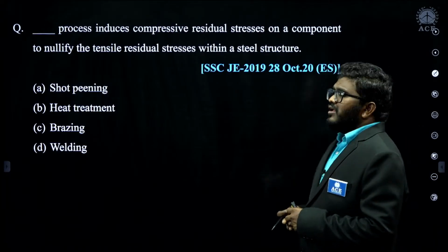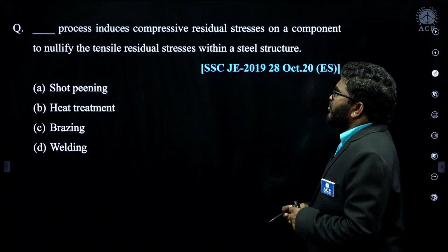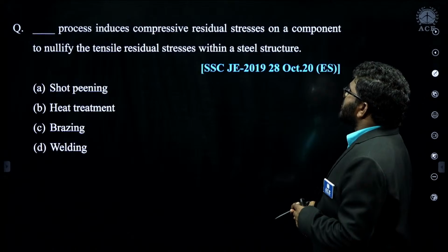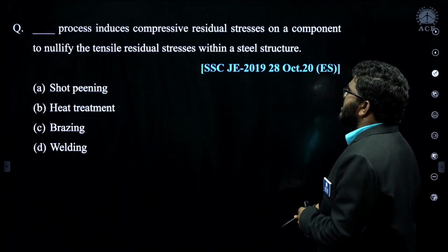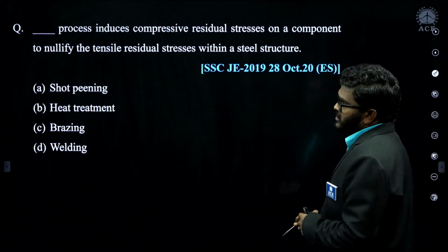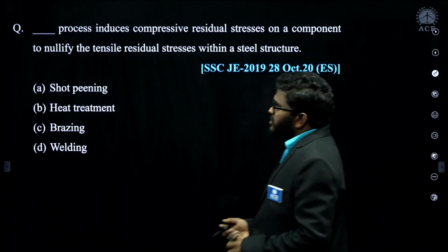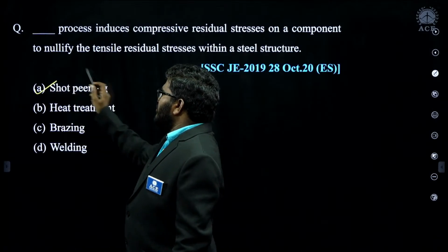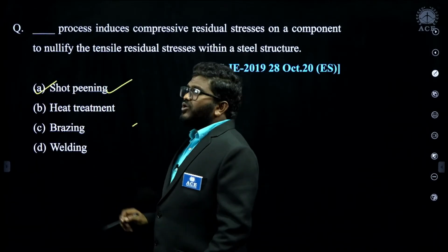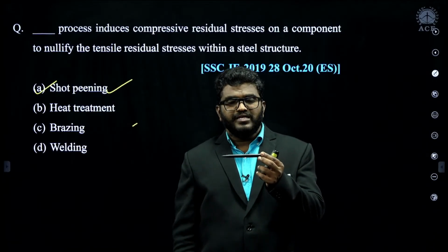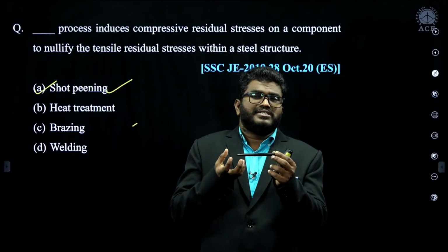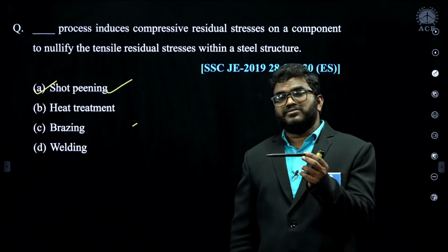Now, which process induces compressive residual stresses on a component to nullify the tensile residual stresses within the structure? That is shot peening. What is shot peening? Suppose this is a workpiece, and I am assuming there are some tensile residual stresses on the workpiece.